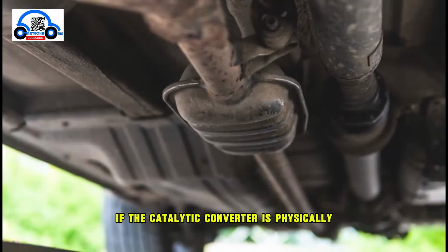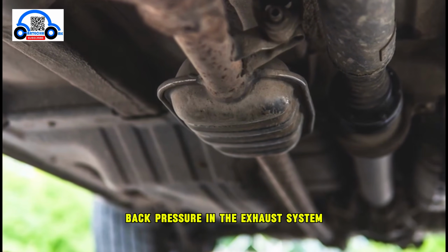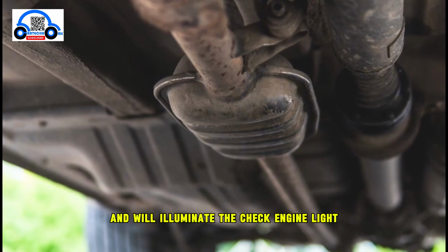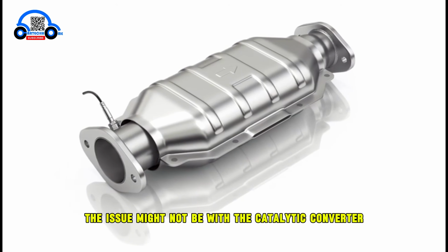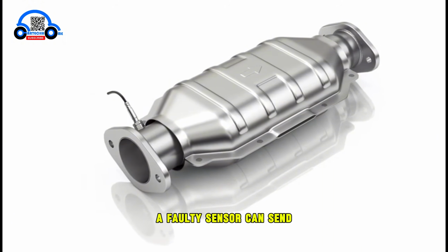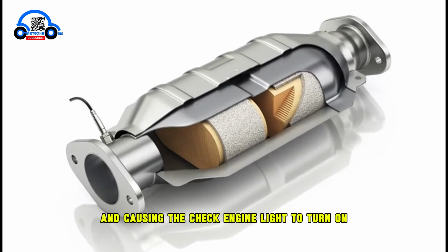If the catalytic converter is physically damaged or clogged, it can restrict exhaust flow, leading to increased back pressure in the exhaust system. This condition is detected by the engine's control unit and will illuminate the check engine light. Sometimes, the issue might not be with the catalytic converter itself but with the sensors that monitor it. A faulty sensor can send incorrect data to the vehicle's computer, leading to a false reading and causing the check engine light to turn on.